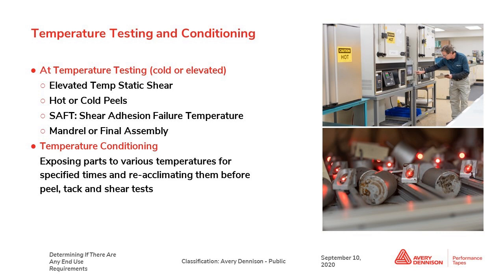Okay, next we're going to talk about temperature testing and conditioning, how they're similar and how they're a little different. At temperature testing, that could be cold or elevated, and you can do the specific test in those situations. For example, the static shear test I just showed you, we could do in an elevated temperature chamber at, say, 85 or 100 degrees Celsius to understand the shear strength at a higher temperature.